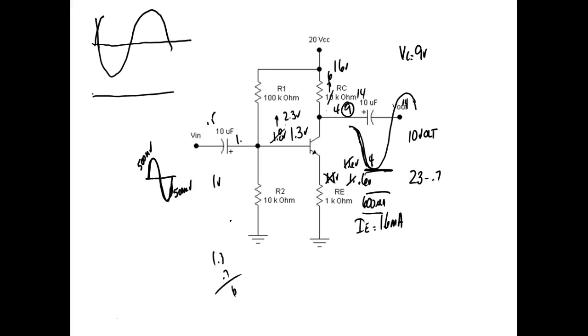It's just a gain. What would be the power gain? Well, we don't know because we don't know what type of load this is. But what you've got to understand is we're going to have to connect this thing to something. So if I connect this to a resistor, what would you expect the gain to do? Well, the gain's going to go down because you're loading an amplifier, right? So right now we're running these things unloaded. We'll figure that out, it's nothing but basic laws to calculate.